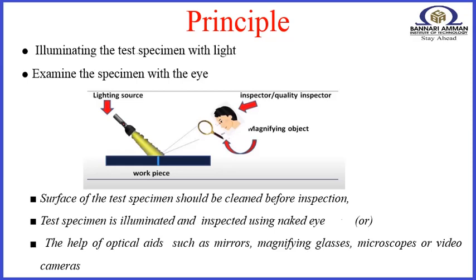The surface of the test specimen should be cleaned before inspection, where the test specimen is illuminated and inspected using the naked eye or with the help of optical aids such as mirrors, magnifying glasses, microscopes or video cameras.